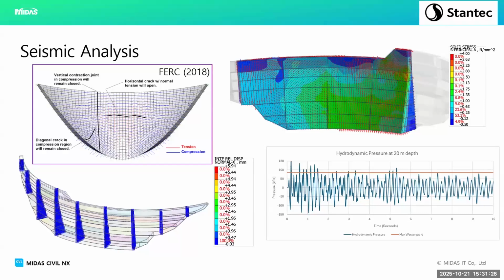But for project specific, what I did is I took Vestergaard's equation and calculated what your equivalent peak stress would be. So you extract your acceleration at the heel of the dam, then you put it in Vestergaard's equation, and you say, okay, where does our time history match with this? And you can see it's not exact, but it gives you a pretty good approximation.